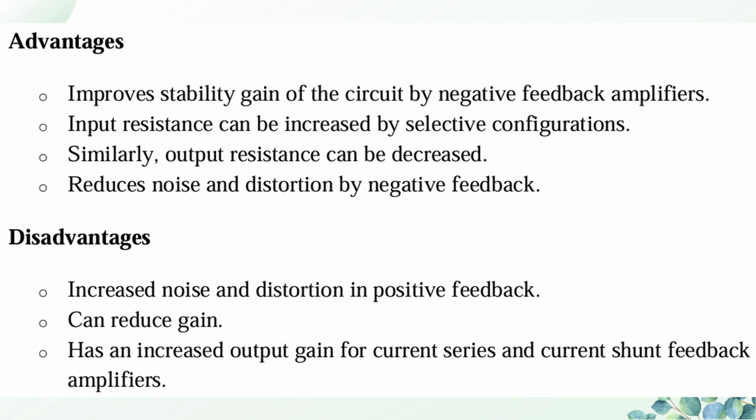The drawbacks of these feedback topology amplifiers are that they increase noise and distortion when we have positive feedback. Also, the use of feedback reduces the gain of the amplifier, and it has an increased output gain for current series and current shunt feedback amplifiers.